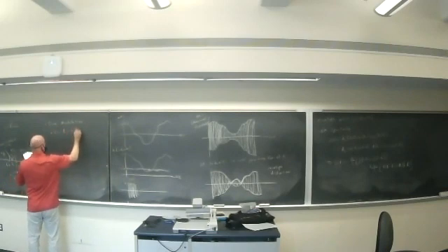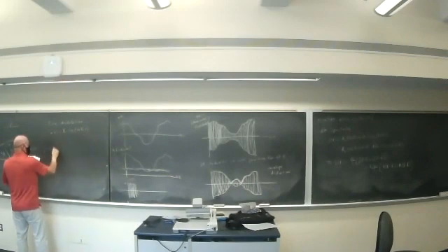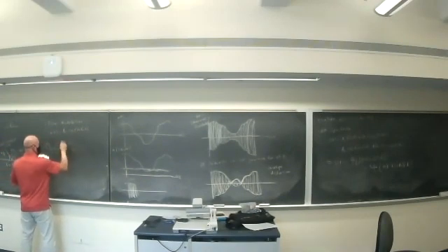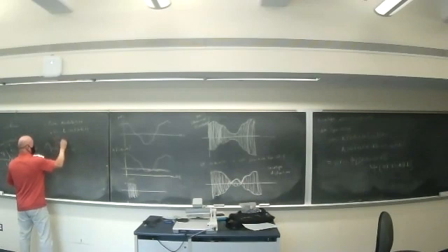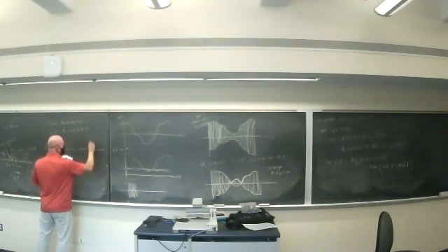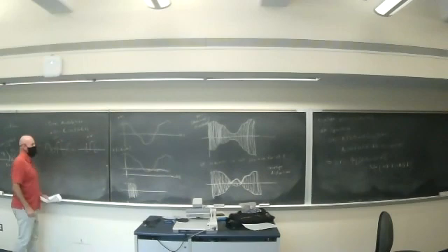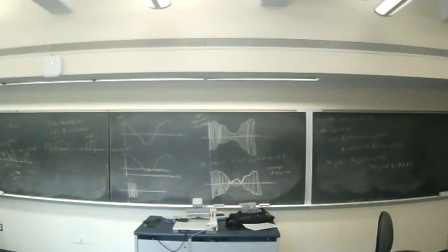So now we're going to let our message be Am cosine of 2 pi fm t. Okay, so m of t, yeah, I had a cosine there. m of t is a cosine with an amplitude Am. In the frequency domain, I get Am over 2. This is the spectrum of our low frequency tone.